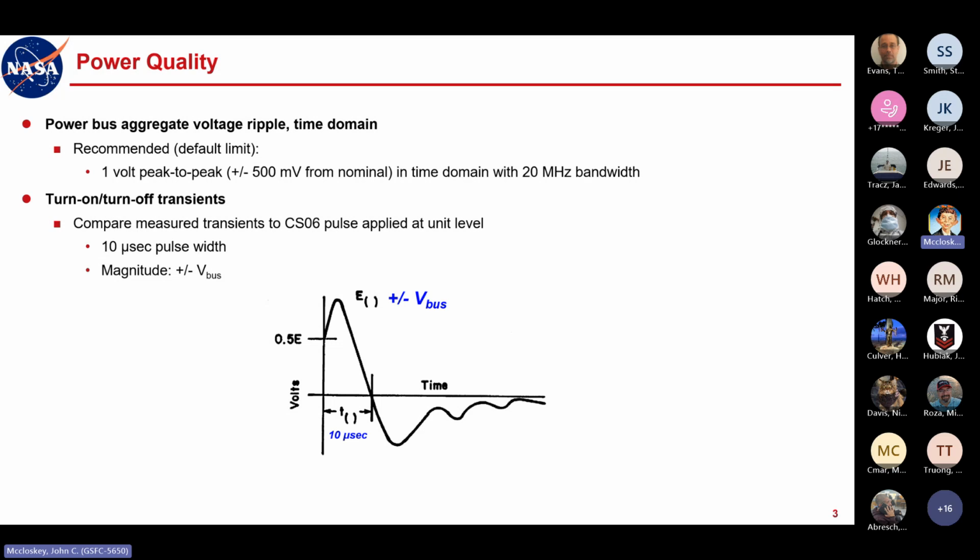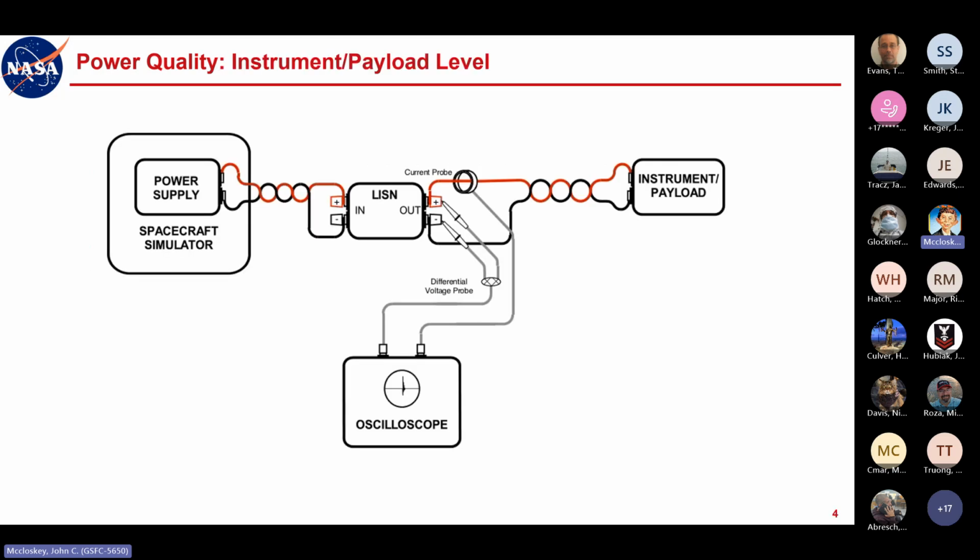Now that's really a GEVS tailoring. That's not in the mil standard. The mil standard, I think, default applies, we walked through that, I think it applies like 200 volts or something like that. So this is kind of standard for how we've done it at Goddard for decades. But this came from the previous version of GEVS, before I had anything to do with it. So that's not how it's specified by default in the mil standard, for what it's worth.